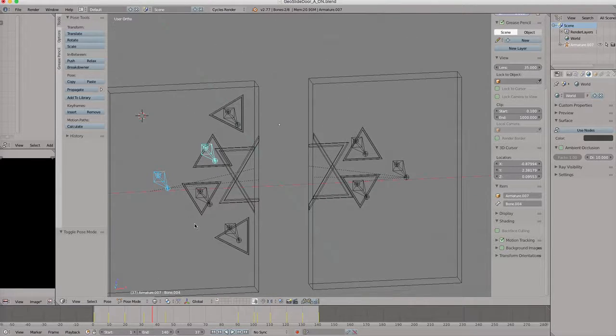So remember, just select all your bones and join them in your mesh tool. I believe you can do that, or you can just hit Control J and join them all. It will make them kind of like a skeletal hierarchy. So you see over in the corner here now, you've got bone 5, bone 6, bone 1.